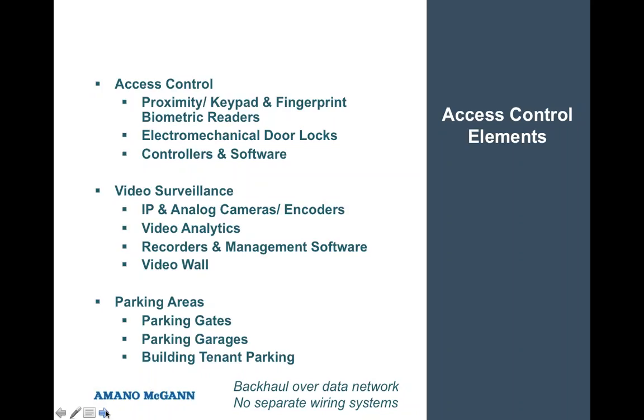So we need to program it, and that comes from a controller. That's actually the software that allows you to program the scheduling of the doors, the number of people, what type of access groups they are, and then you put the reader on every door. If it's one that you want to be controlled from both sides of the doors, you typically would use a mechanical mag lock, and if it's one that you want to have free egress from one side, you would use a strike, and those are just mechanisms to lock the doors.